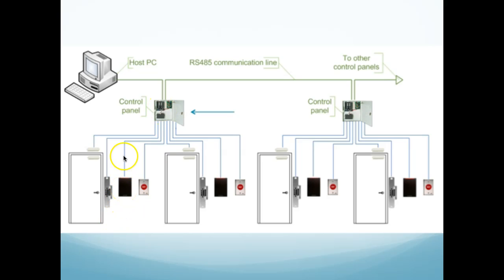Requests are made at the door, decisions made at the panel, and they come down and lock or not unlock the door, and then they store that history of what they did and who they did it for, the badge they did it for, in here, so that if indeed this is broken right here, this line between the host and these panels, they continue to use that last information that Brian was allowed in the door. He's still allowed in the door. They use that last information to make the decisions; they don't need the host other than for updates.